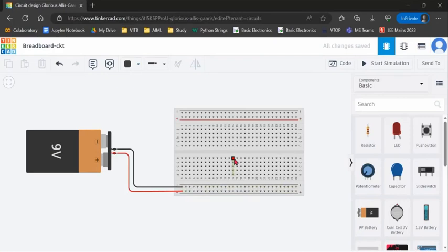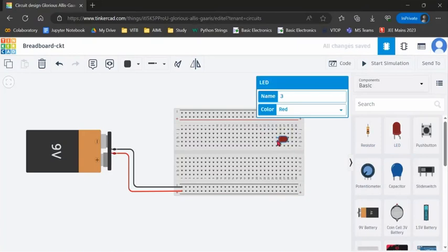Whenever we need to connect an LED, we'll be taking the LED. These are the vertically sorted lines, which means these two lines, 21 and 22, are not sorted. But we can't place the LED likewise because these pins of this vertical line have the same voltage. If we connect this LED likewise, both the LED terminals are connected with the same voltage. So there will be an incorrect connection.